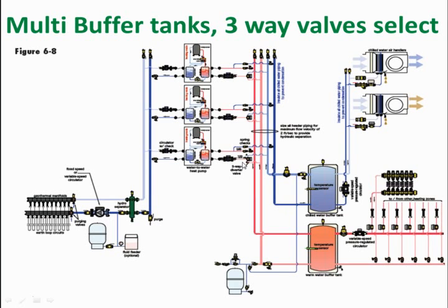So that's what's changing on this: now we put in the second tank. Now we've got the ability to store some energy for both the heating and cooling loads, and we're doing that by toggling this three-way valve here. We've put some check valves in there so we don't get backflow, because you're going to have to choose with this one. Again, you're choosing between one or the other. You can't feed both of these lines simultaneously, so we want to make sure we've got some check protection there so we're not going to backfeed from the hot and cold there.